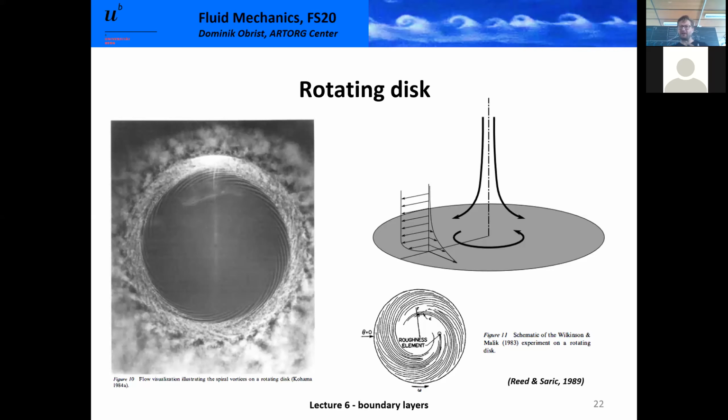These boundary layers are important from a technical point of view because they're much more unstable than, for instance, a Blasius boundary layer. They are much more likely to create turbulent flow than classical two-dimensional boundary layers. You see here on this visualization on the left, these are actually unstable structures. Out here, these are turbulent structures, where it's like gray, like this foggy structure, where you have more of these spiral structures. This is like the onset of an instability. But we'll look into this in 3 weeks.